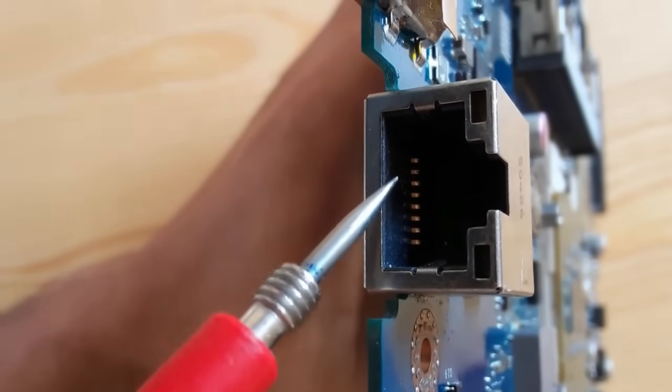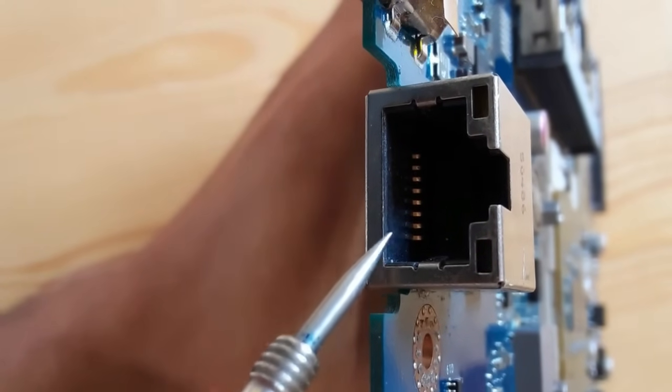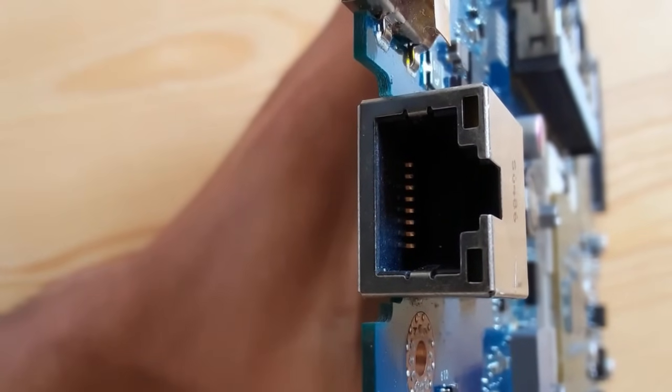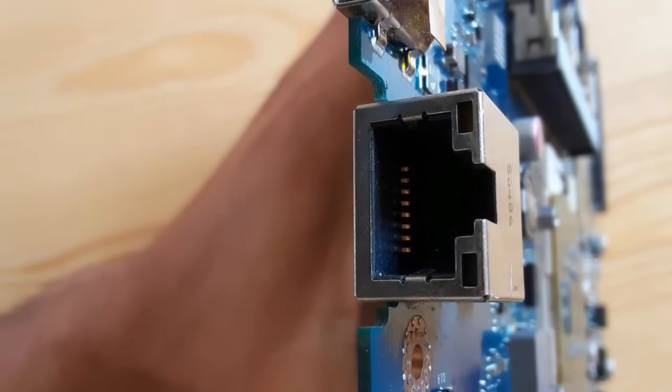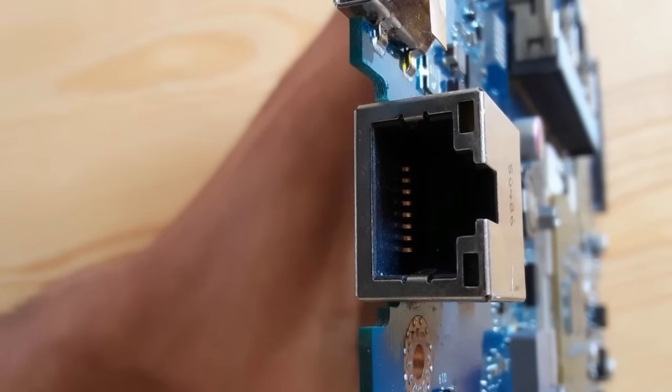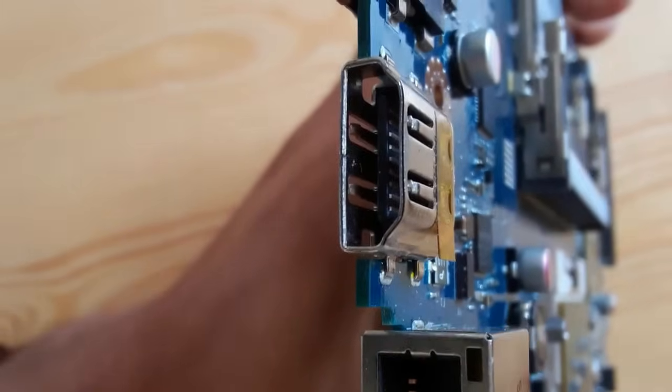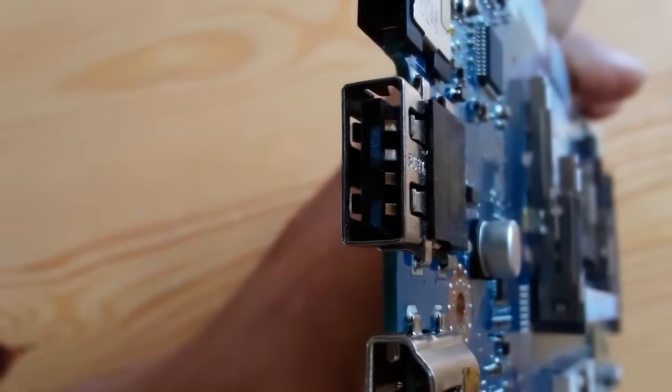The same working principle also applies for other connectors like RJ45. As you can see, this is RJ45. It contains about 8 pins or 8 terminals. The terminals should be good, should not be damaged or bent. If you have any part that is damaged, you should replace it.